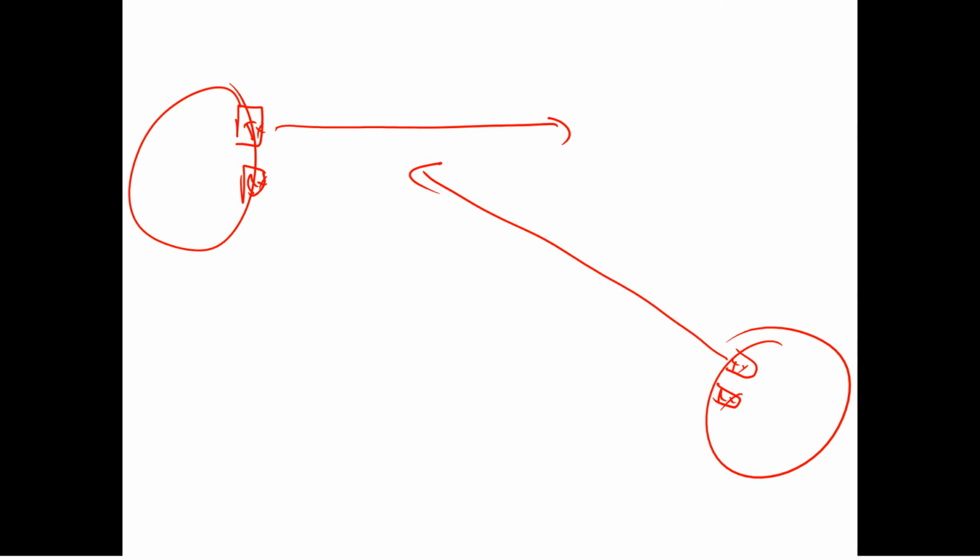Now this is all going to be random, because what has to happen is robot 2 has to transmit at the same time that robot 1 is waiting for an echo response. So it's not extremely likely, but it could happen, especially if you're looking continuously. Again, that's another reason to measure 5 in a row every time you do a distance measurement, and confirm, hey, this looks like a real object, and not just some sort of false echo.